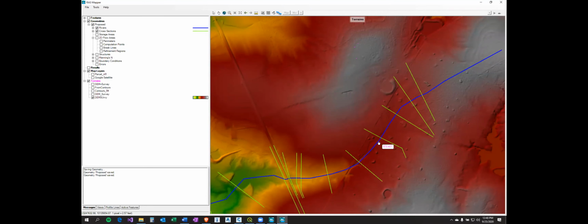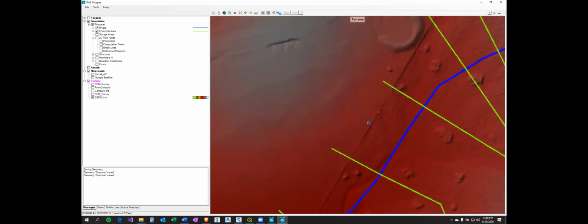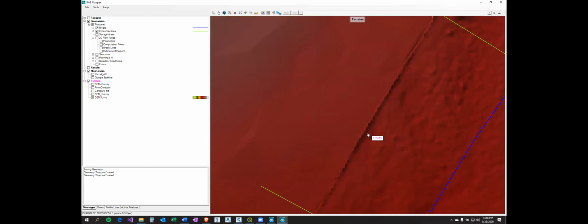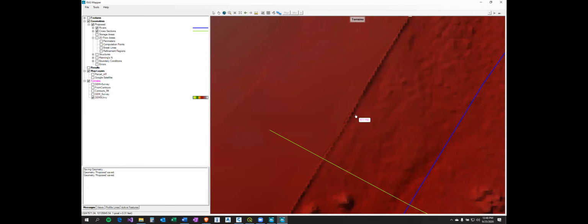What RAS is using is called an HDF5 file. It's a hierarchical data format file. It's a supercomputing format that they've aggregated and adopted. So when that surface is built inside of RAS, it does not care about seams and spatial resolutions. You can have 1 foot resolutions on your survey, and you can have 3 foot resolutions on your LiDAR data, and you can have 10 foot resolutions a little further out, and it doesn't care. It tries its dangedest to seam them, and sometimes you do have seam stitching errors, but that's because of the data. That's what Adam's showing right now.